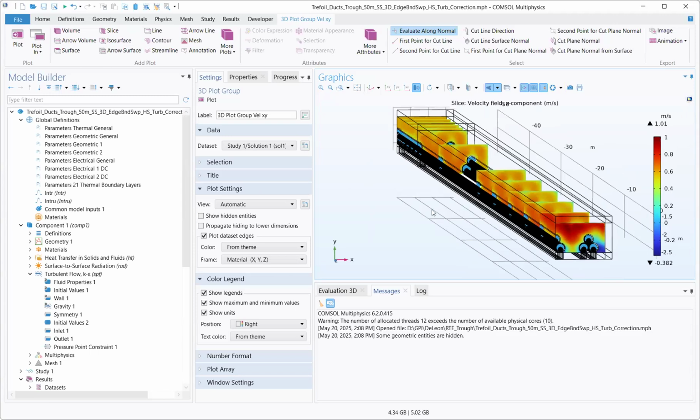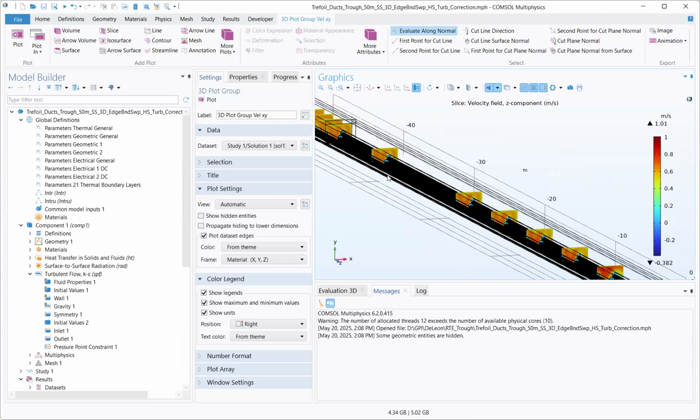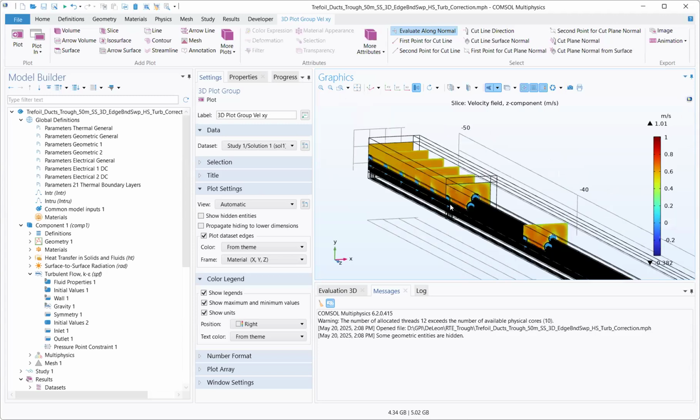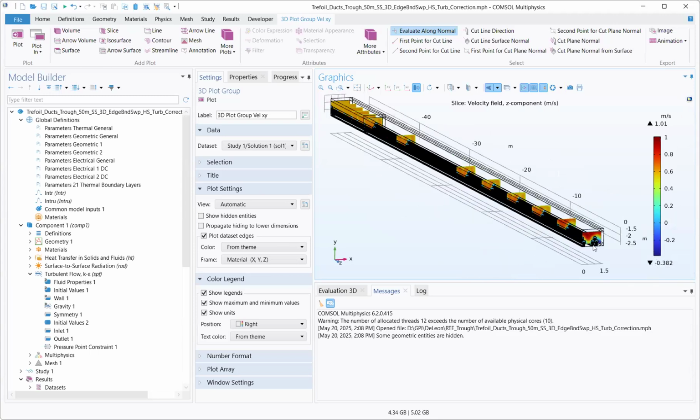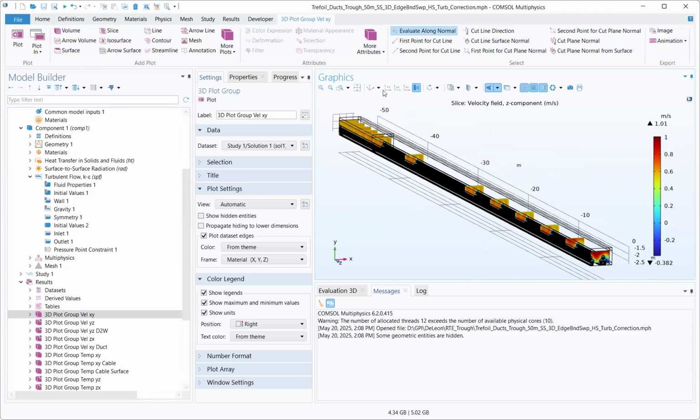And then also, I forgot the full length of the project, but in this case I'm modeling, I think, 50 meters, and the customer wanted something like 300 meters. It's not necessary to model 300 meters because we know the fully developed region is less than that. So we need at least the fully developed region and some extra length, but not much more than this. 50 meters was sufficient. So what we need to do is we need to not only mesh.